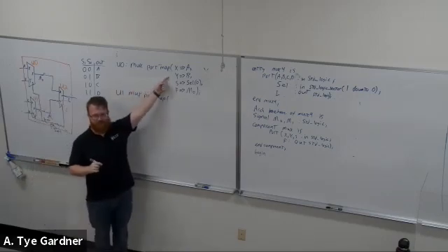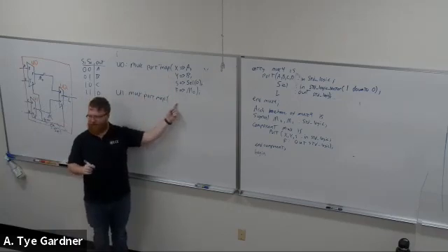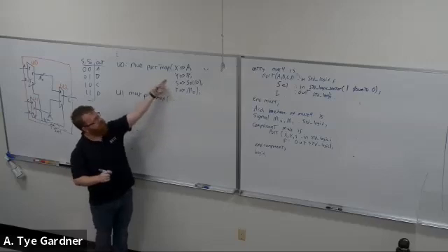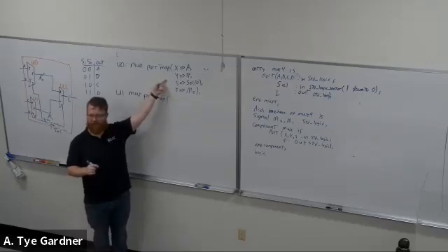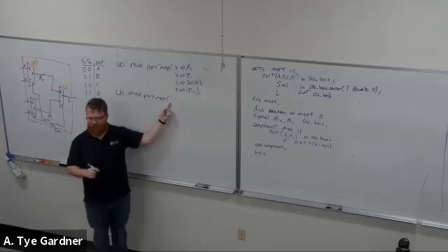This is an explicit port map. This one is going to be an ordered port map. So the cool thing about the explicit is it does not matter the order in which I assign the ports. And I do not need to even assign all of the ports. Ordered port map, neither of those is true.